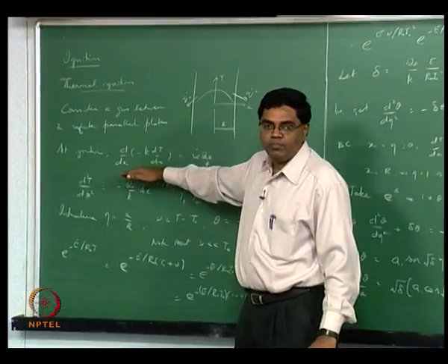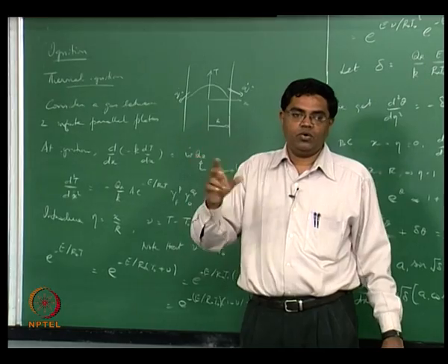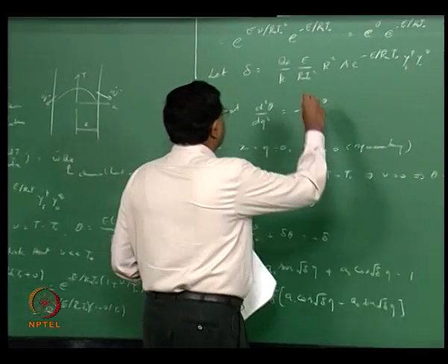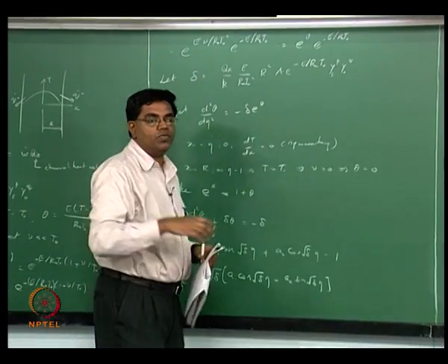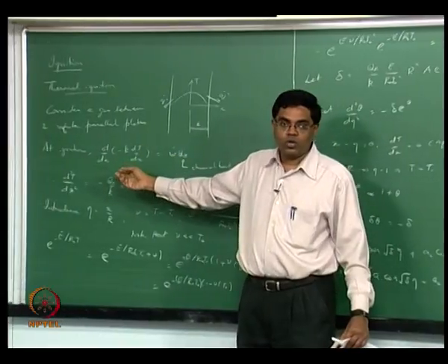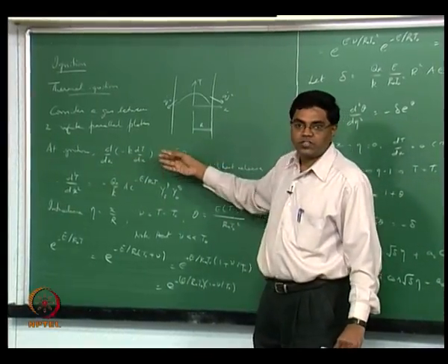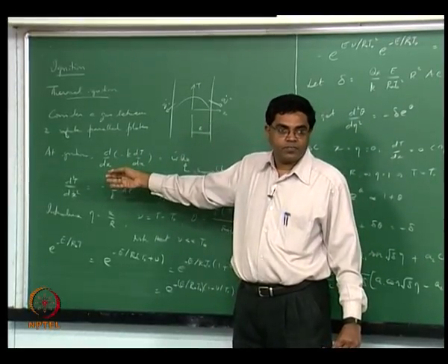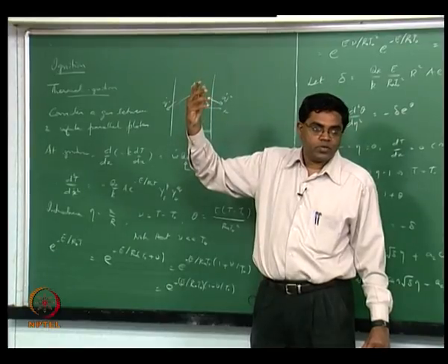So this equality begins to happen for a certain minimum critical value of capital R, and therefore a corresponding delta, beyond which ignition will happen. And again this equality won't hold good, because you will now have more heat release due to chemical reactions than the conduction at the walls, and then the reaction grows, and then you now have an ignition, right.